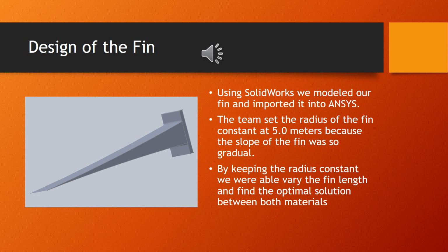Using SolidWorks, we modeled our fin and imported it into ANSYS. The team set the radius of the fin constant at 5 meters because we wanted the slope of the fin to be gradual. By keeping the radius constant, we were able to find the fin length and find the optimal solution between both materials.